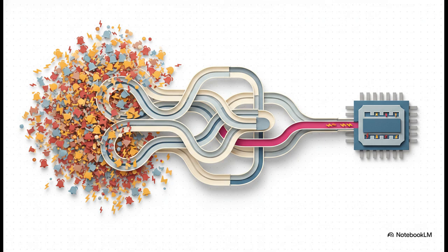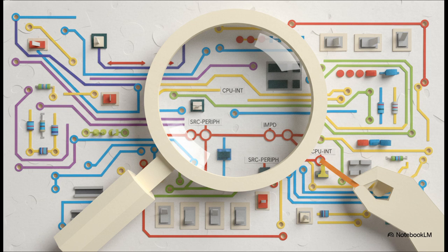But you might be wondering, how does this actually work when the chip generates 71 different hardware alerts across the board, but only has 26 interrupt slots available per CPU? Well, that's exactly why this matrix maps them so flexibly. It routes the most critical alerts from your peripherals directly to the available CPU interrupts, making absolutely sure nothing gets bottlenecked. To configure or troubleshoot these reflexes, embedded developers basically map their peripheral source to a specific CPU interrupt number, and then they query the specific status register to verify exactly what triggered the event. It gives you this amazing microscopic control over exactly how your hardware prioritizes its tasks.